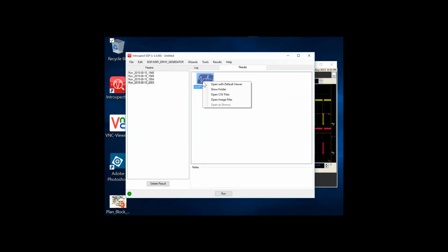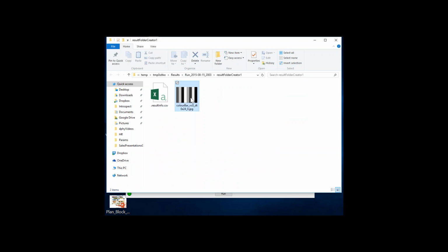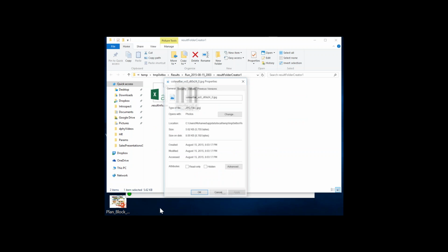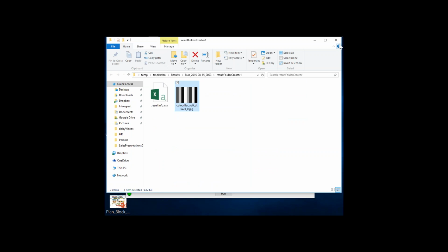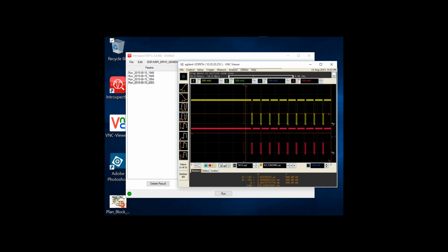This is a real picture, so it's compliant at the protocol level, at the CSI2 protocol level, as well as at the electrical level, as well as having good electrical properties for stress testing the analog portions of the receiver. So this is an actual complete image that's completely valid. So that's a brief overview of the CTS colorbar pattern and why it's useful for receiver testing.